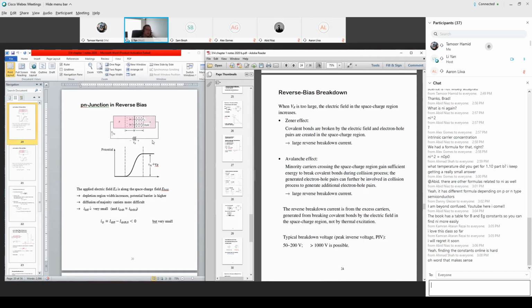We said that. So this V_R is the external voltage under reverse bias. Previously we said that with a much, much stronger reverse bias, the drift current goes to zero, and the diode current just goes to equal minus I_S. But that's very ideal. What ideal? It's under the condition that reverse breakdown didn't occur. Well, here we learn the new phenomenon.